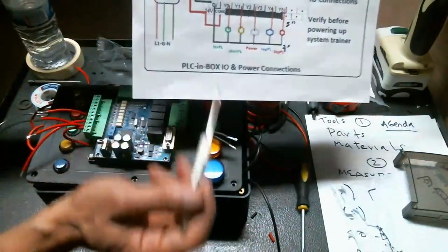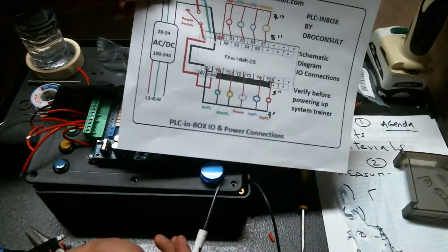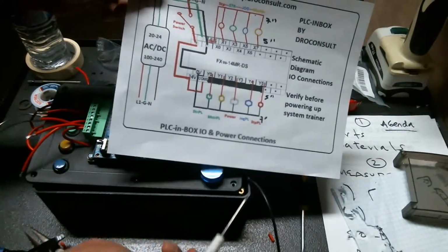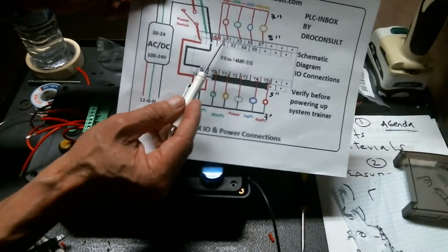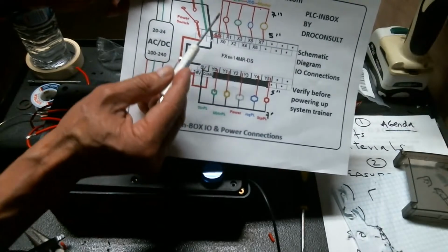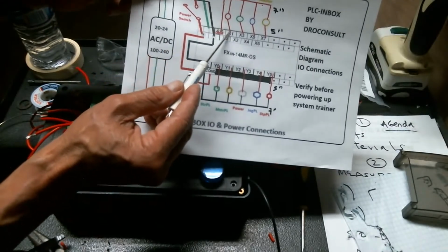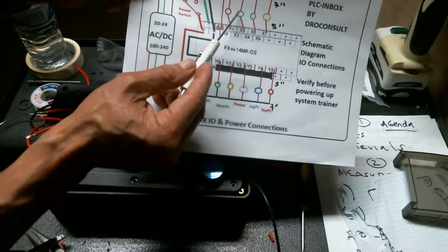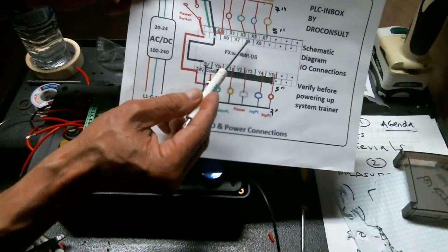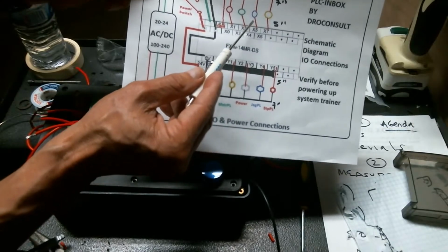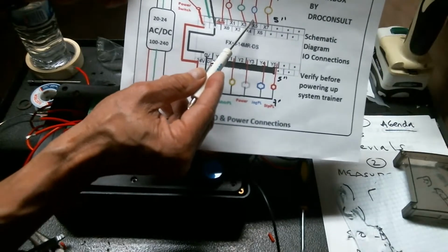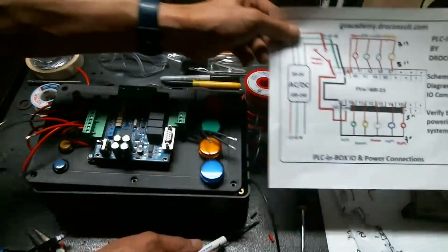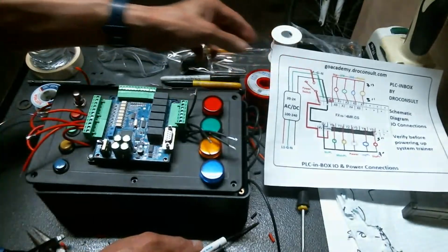If we go by the schematic, and you might want to do it this way, what we need to do is that in terminal input X1, you're going to bring the stop wire, right? In terminal input X3, you're going to bring the start wire. In terminal input X5, you're going to bring the next one, and then X7 the next one. So however you want to do that, let's kind of follow what I have in the schematic.